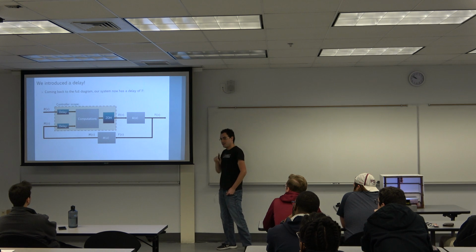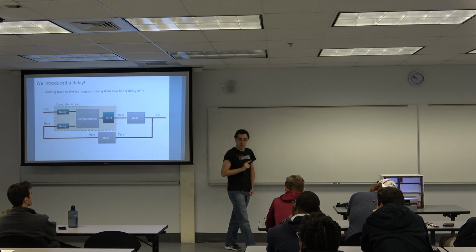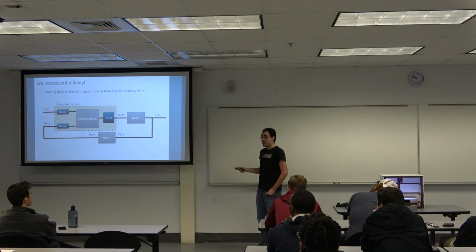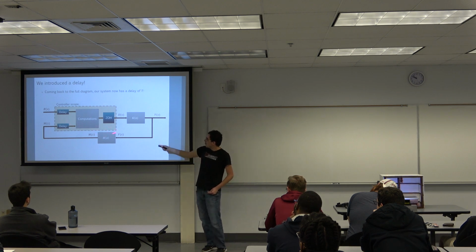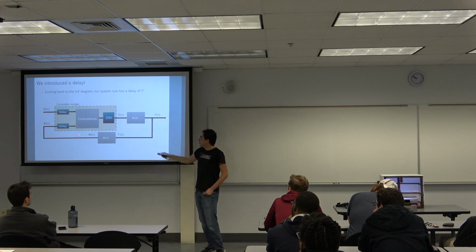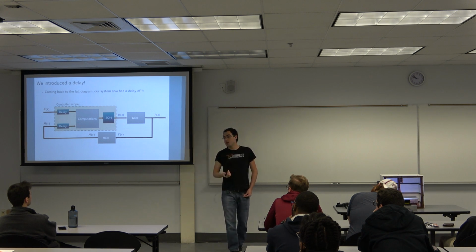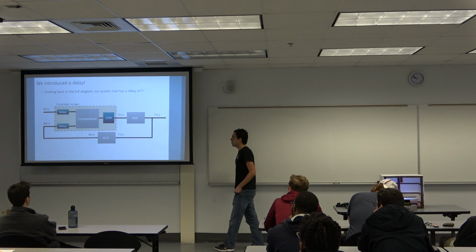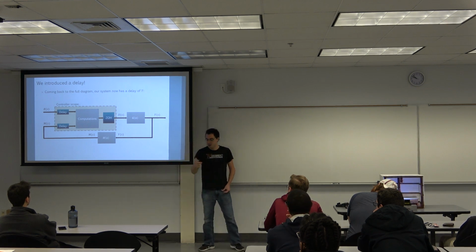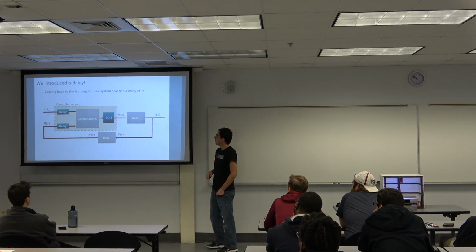And I just want to highlight that, as I said, we're computing numbers, but it takes time to compute the numbers, which means that we're introducing a delay. So every time we hold the signal to the plant, the measurement is available already, given the restrictions of the analog domain, but the measurement is always available. But I can't use this measurement while I'm computing. So this means that I'm introducing a delay of capital T, which is also going to have some impact, depending on the sampling rate, on the characteristics of the controller, which we must include.